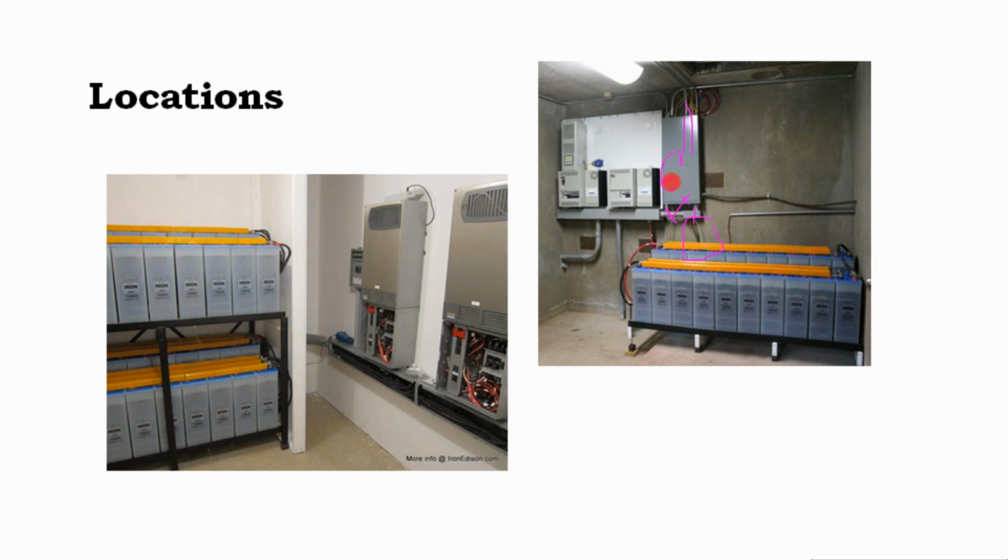Well, actually, it would be fine either way because they're to the right or to the left of each other. But let's say I wanted to put this electric service panel underneath here. And so we have one panel that's serviceable, another panel that's serviceable. You couldn't have more than 6 inches of depth. And so the problem is now we have these batteries sitting in front of this service panel, and even though it's dedicated electrical space, there's 30 inches of batteries sticking out in front of this service panel. And so that would be a code violation.